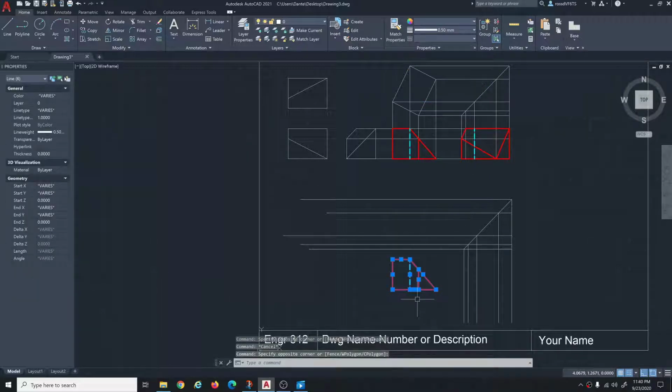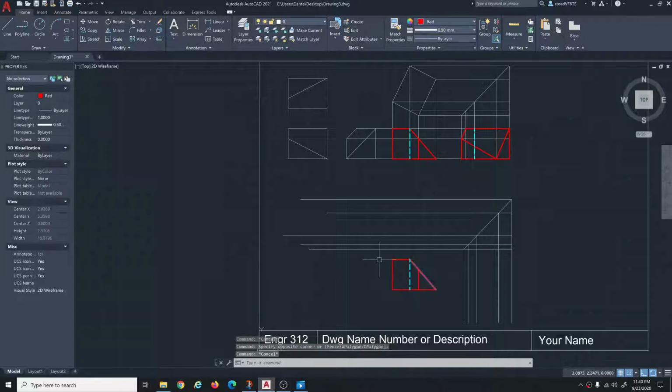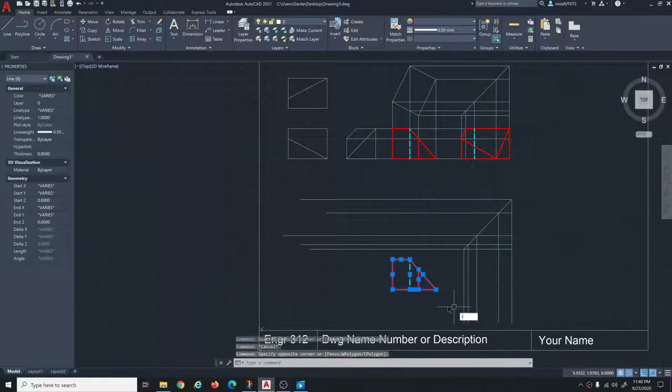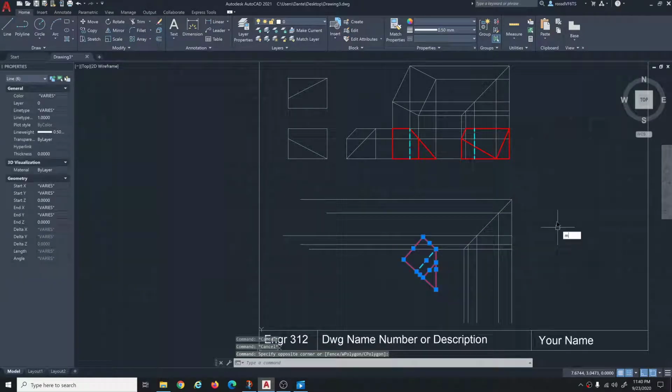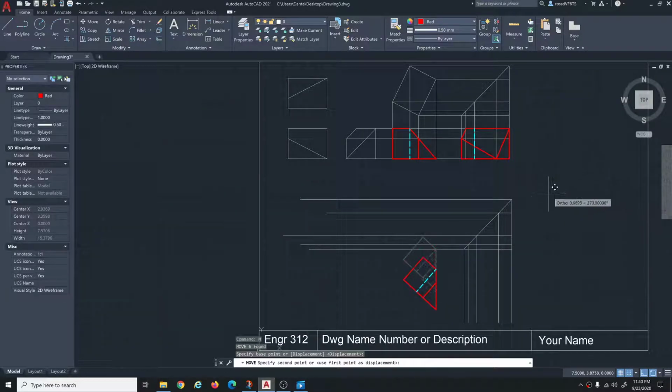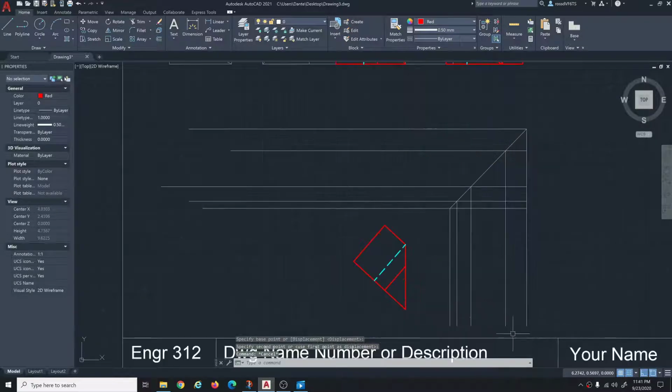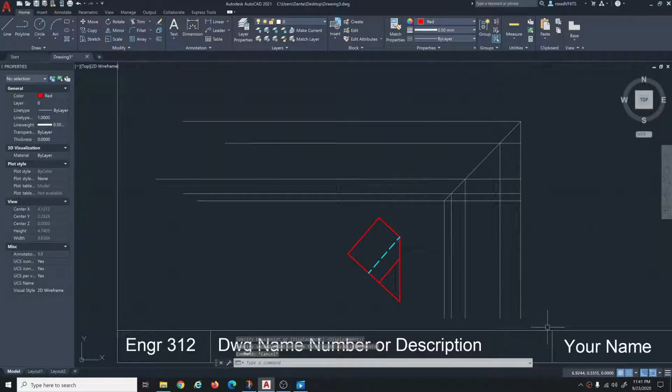Think back to that video I was showing you a moment ago from Rhino. So now we're going to take this guy and rotate it about this point, and we want to do reference and center point, first reference point. Then with ortho on, it'll snap up like that. Okay, now you can grab it and just do a move and bring him down so he's not in the projection lines. Okay, now it's time for a bunch more projections.